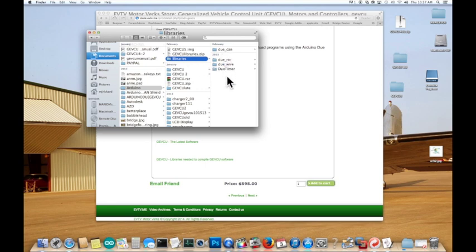These are now available to any Arduino program I happen to be working on, and I can include these in the software with include statements and then call functions out of them. And so, for your purposes, if you download the JEVCU software and compile it, you have to have these 4 libraries in your libraries directory, or it will not correctly compile.